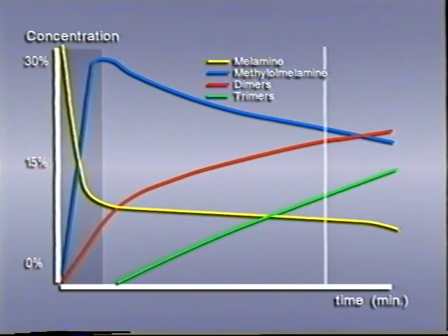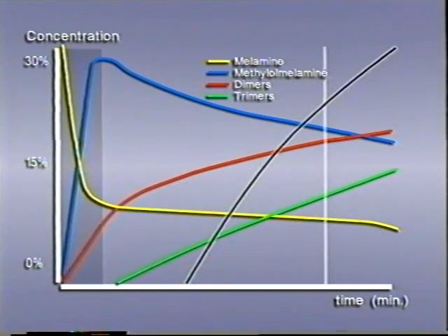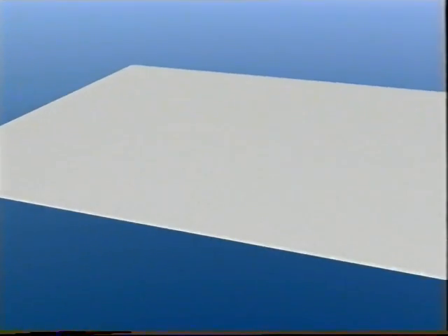The duration of the condensation phase determines resin characteristics such as viscosity, reactivity, and shelf life. Measuring empirical solubility parameters such as water tolerance usually determines when the condensation phase has ended. The resin's positive attributes are not possible, however, without the introduction of a second component, the paper. Magnification shows the cross-section of a typical white decor paper, to which we now turn our attention.